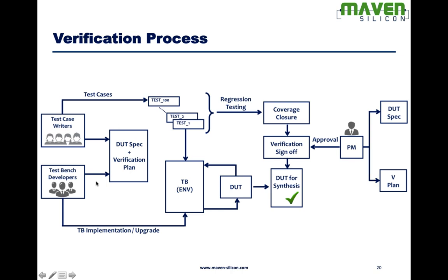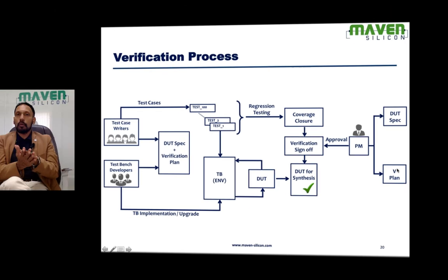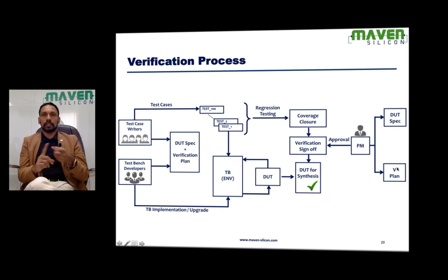And all these people, they report to project manager. And he's the one who is going to look at DUT specification and define verification plan. This verification plan will have all the details, the design features, test scenarios, coverage model, self-checking strategies. It's going to have all the details about the complete verification process, how the simulation is going to happen.